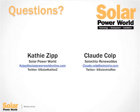Okay. I'm not sure if this maybe is where they were going, but they're wondering if the Arcom functions as a smart combiner. Are data channels for current voltage available for each string? So at this time, and as far as I know, there are no plans to add current sensing to the Arcom box. It has current sensing for the arc fault detection circuitry only. So it is not a smart combiner box.